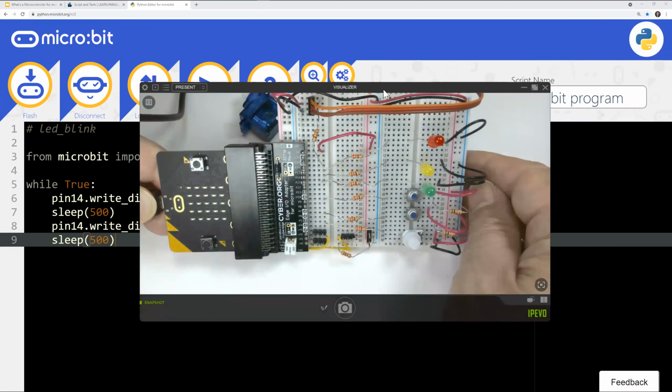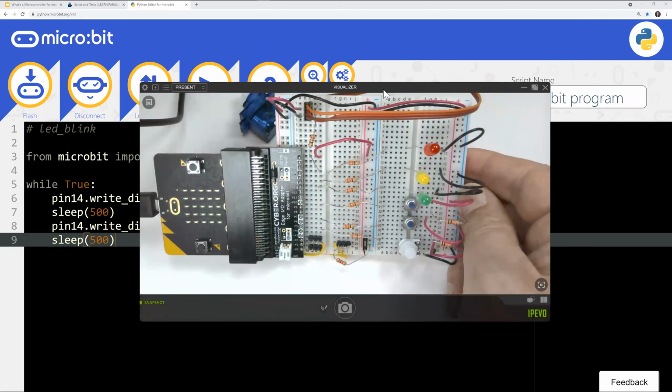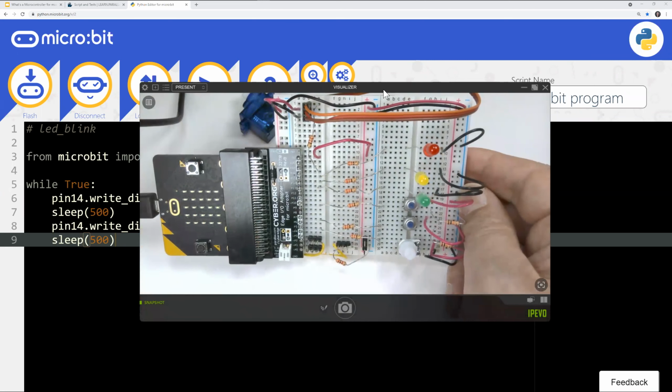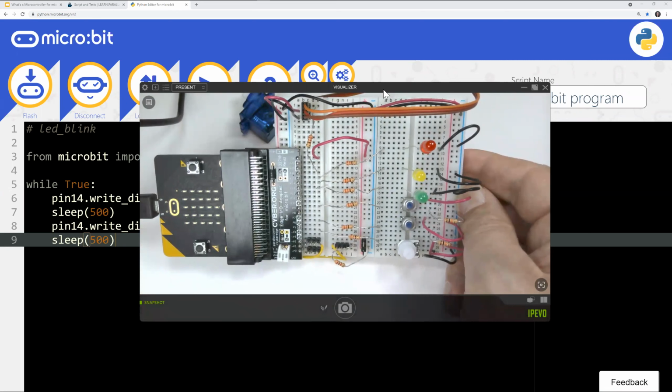So it could be that 2 of the resistors are touching each other. Although I'm trying to work out in my mind if that would cause the yellow to blink. I think I'd expect the green to blink in that case. And then the other thing is, if you follow from P13, see here, my video froze. I'm waiting for it to unfreeze.